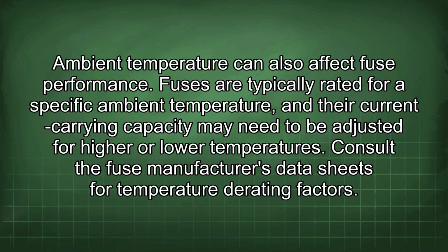Ambient temperature can also affect fuse performance. Fuses are typically rated for a specific ambient temperature, and their current carrying capacity may need to be adjusted for higher or lower temperatures. Consult the fuse manufacturer's data sheets for temperature derating factors.